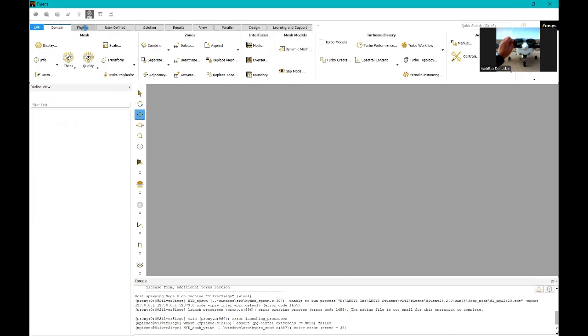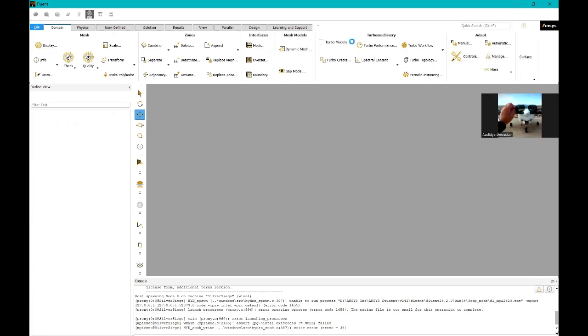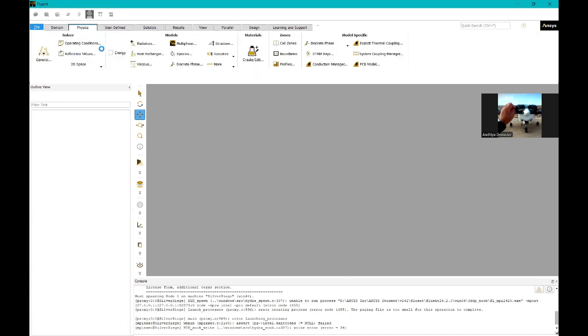So basically, this is the Ansys UI for the Fluent Solver. Just mind the fact that this is Ansys Student, not the actual version. The actual version costs lakhs. This is free. As you can see here, there is a section for turbomachinery that is able to analyze all the properties related to turbine engines, like turbo models, turbine performance, and so on. Also, here you are able to incorporate all the models that you want: acoustics, structure, species. So basically, you could also run multi-physics simulations with Ansys Fluent. That is the neat part about it.